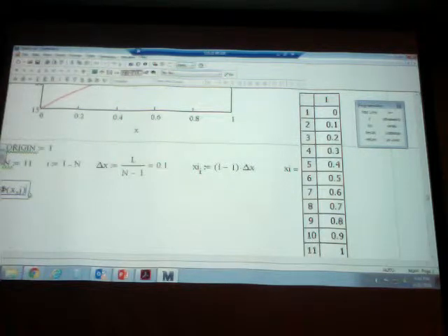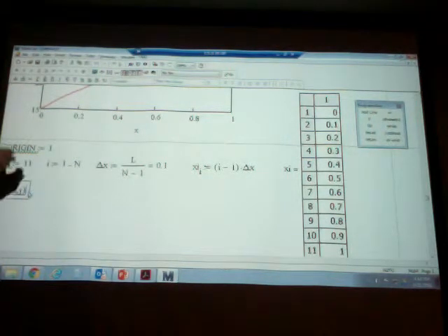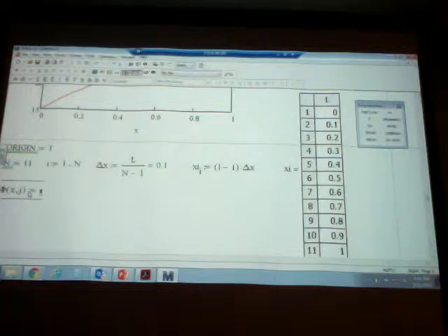Well, j is a sub-index, but in MathCAD I cannot define an array of functions unless I do it manually, unless I actually insert a vector and go element by element and introduce it. So I'm just going to make j another argument in this variable. And what is this? It's x to the power of j minus 1.